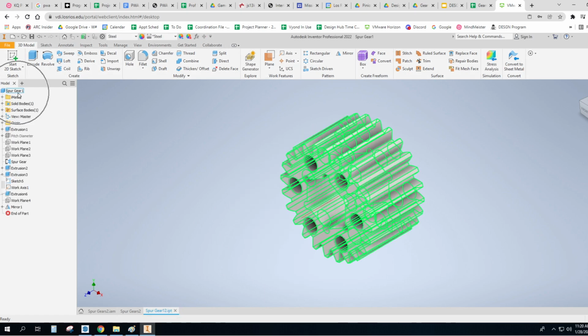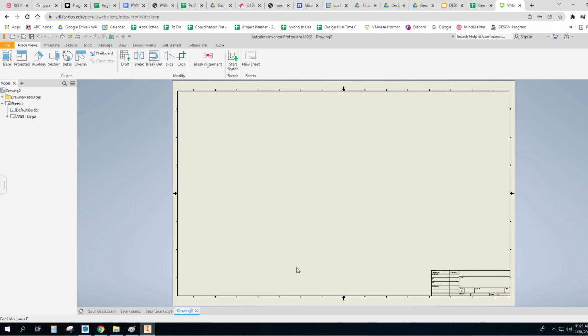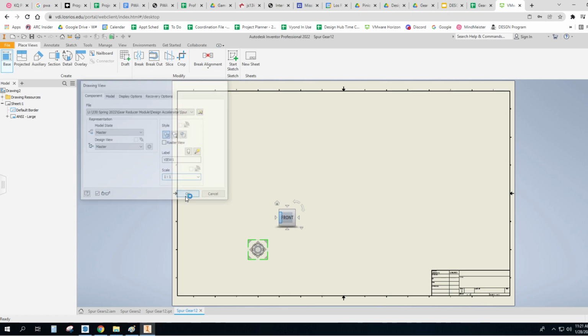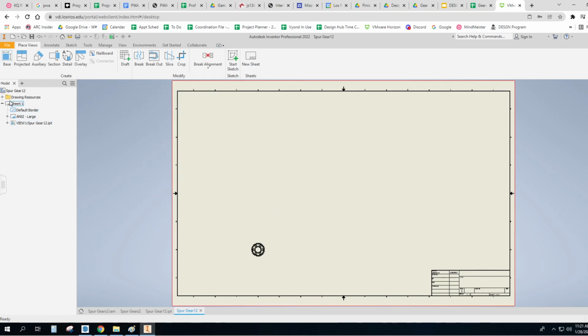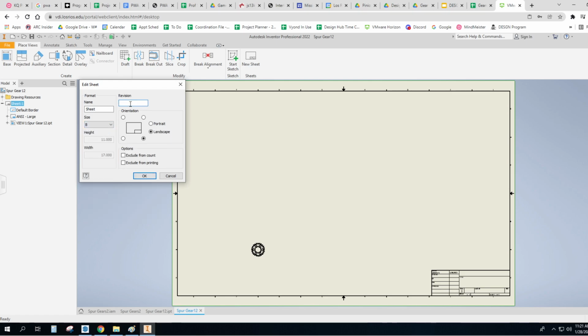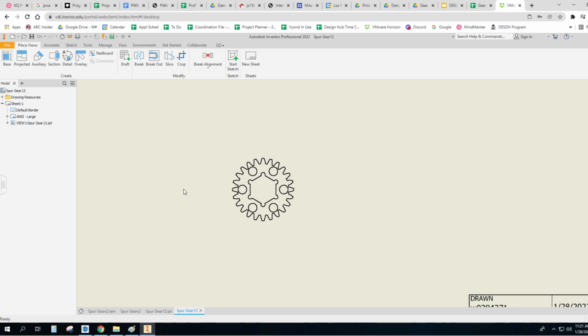Okay, so I go to the top, right click, create the drawing, front view, and I'm going to have it as 1-to-1 because this drawing is way too big. So I have to go through all that again, because I have not given you a template. If you remember how to make a template, you can do that. But I figure that's part of what you're supposed to know how to do. Okay, so there's that one. Now I can make a section.